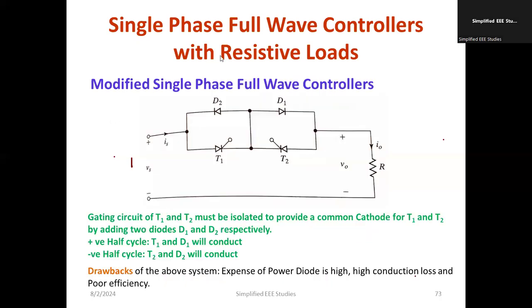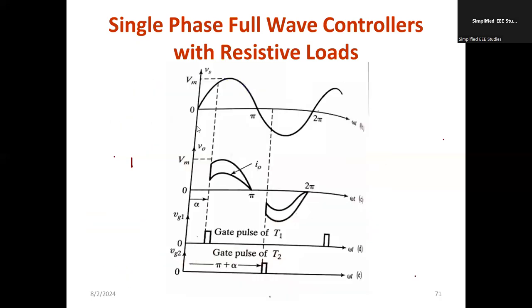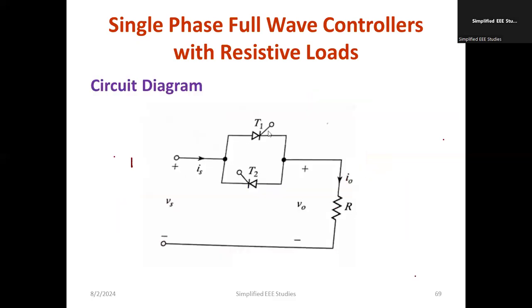Okay. Now the problem is in this particular circuit, which you can observe, there is no isolation between the thyristors and the firing circuit. Where is the firing circuit? Can you show me? Here we are going to provide the VG1, right? Here we are going to provide VG2. These are called the firing circuit. Okay, that will operate with a very tiny voltage, maybe less than 5 volt.